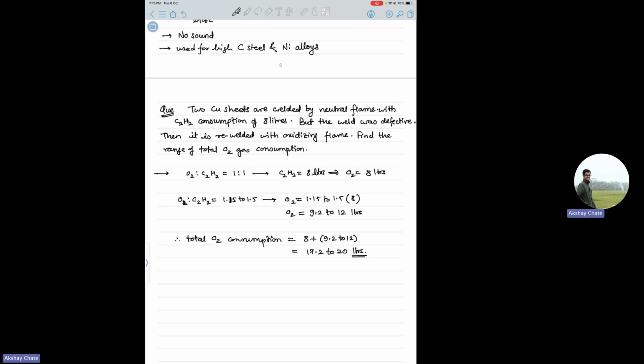There is another welding process also, which is called thermit welding. Okay, so basically here you used oxygen and acetylene combustion as a heat source for melting. There you use iron oxide plus aluminium as a mixture, which is called thermit mixture. So you basically heat it up to a certain temperature, and then an exothermic reaction takes place between those materials, and then you get the liquid iron. Okay, so we'll talk about that.